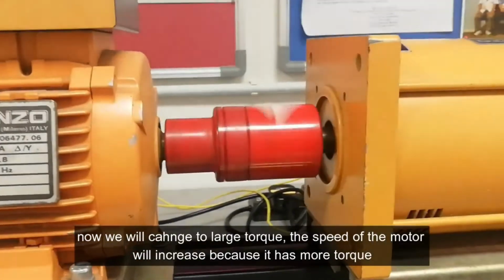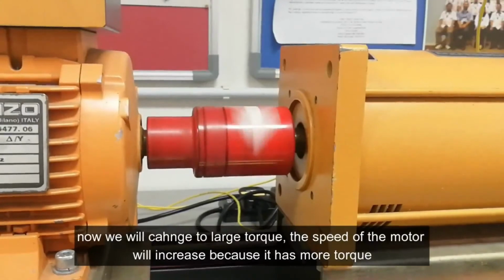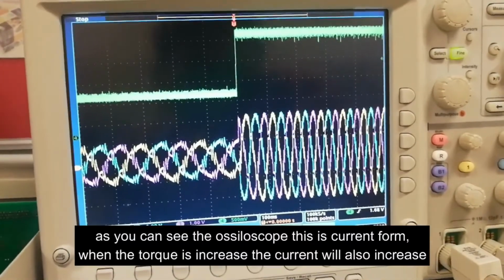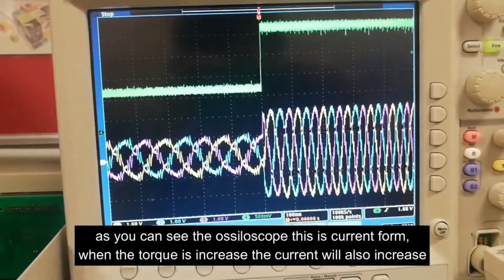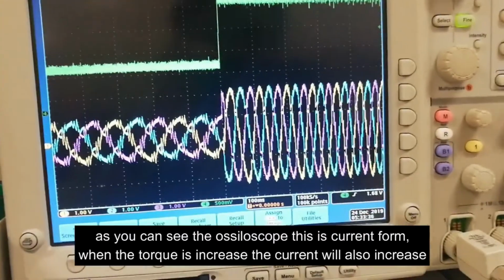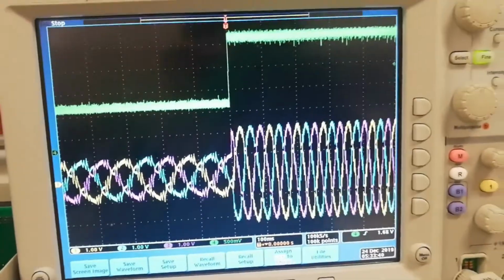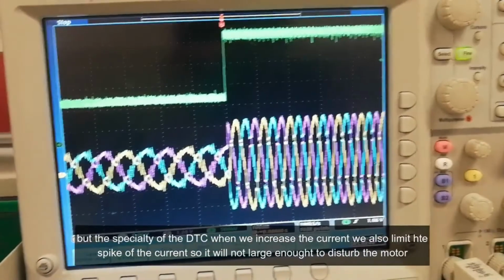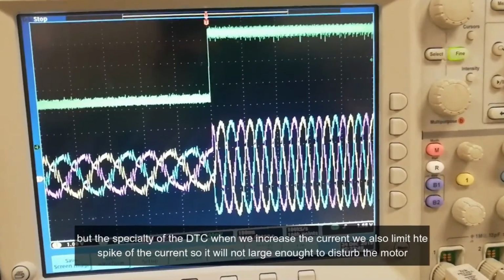The speed of the motor will increase because you have more torque. So as you can see in the oscilloscope, this is the current waveform and the torque waveform. When the torque is increased, the current will also increase. But the specialty of DTC is that when we increase the current, we also limit the spike of the current, so it will not be large enough to disturb the motor.